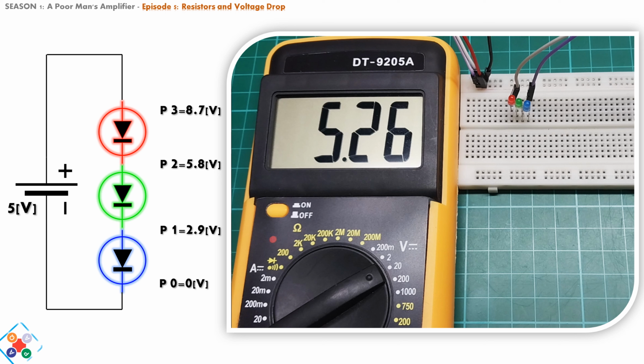The measure of resistance that such external force has to overcome, in order to push the current through the component, is called voltage drop. In our experiment we used an LED diode. From the electrical specifications document we know that an LED diode requires at least 2.9 volts of something called forward voltage in order to glow. So, to put things into perspective, our LED diode has some internal resistance, and in order for current to flow through it, the power source has to put out voltage that is equal to or higher than 2.9 volts.